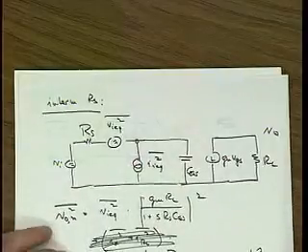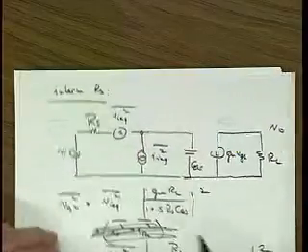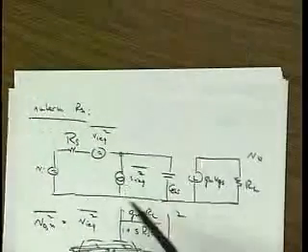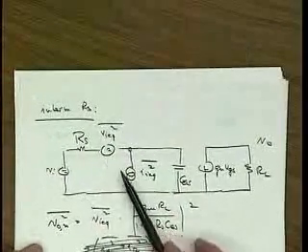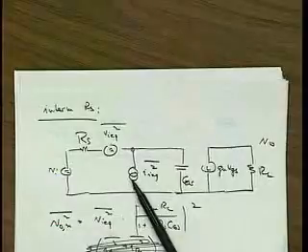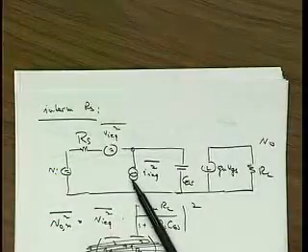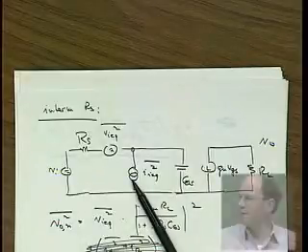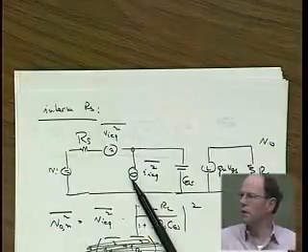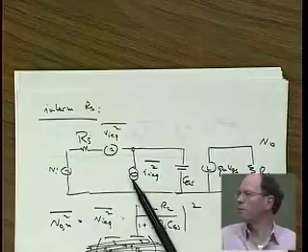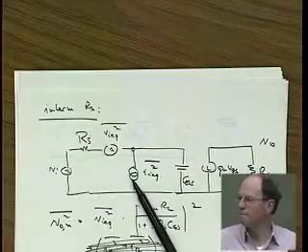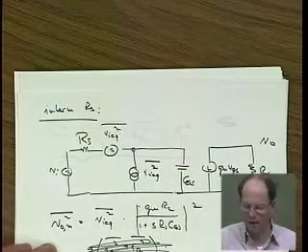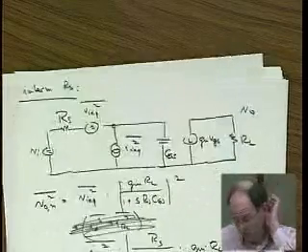And so in cases where you do this calculation and you find that VIEQ and IIEQ contribute about comparably to the overall noise, then it is safer to just abandon these input referred noise sources and calculate the noise from first principles, right? Going to the output noise and calculating for the particular value of RS.